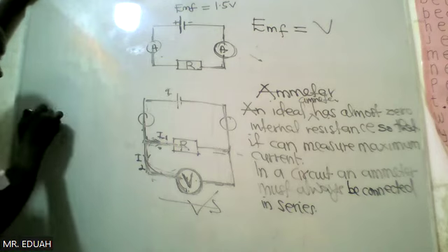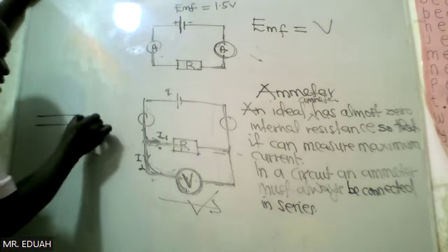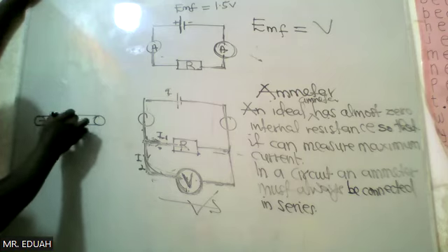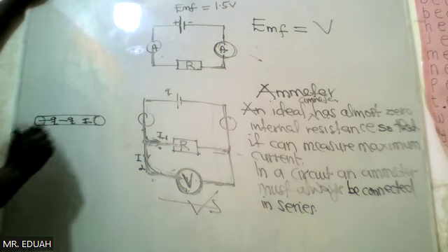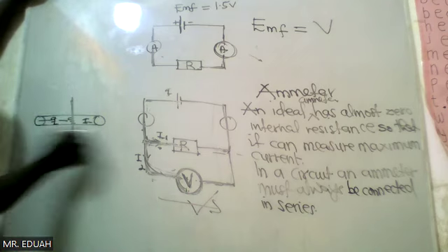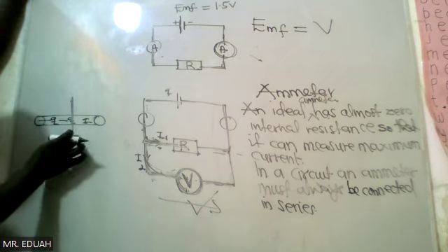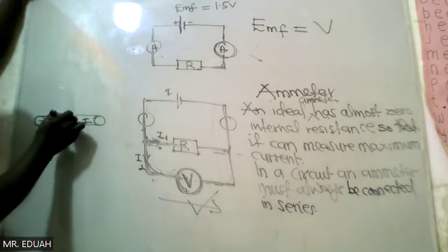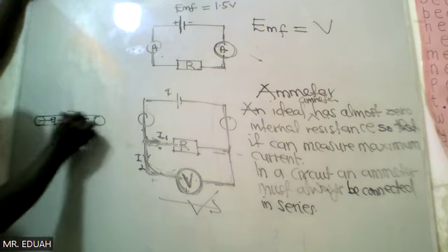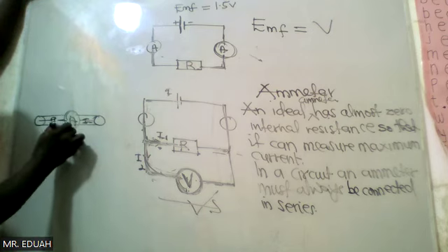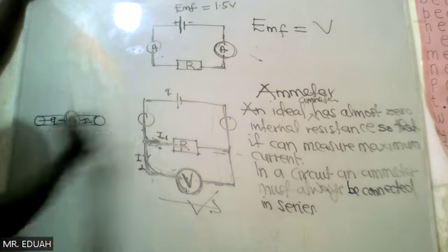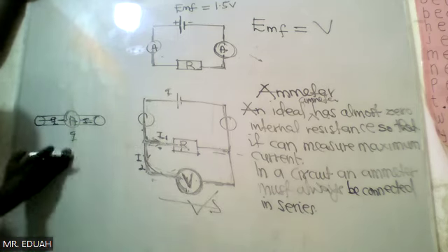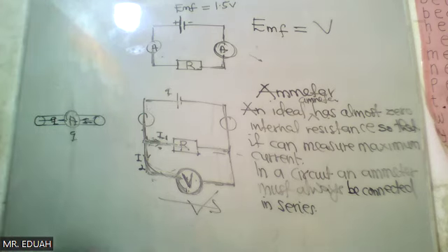And this is because the current, the charges, always flows through the volume of the conductor. So if you want to measure how many charges are crossing every second, then cut the conductor and connect the device to the conductor. And this would measure the number of charges crossing to give you current. So it must be connected in series. The moment you break the circuit and push it in, it is in series.